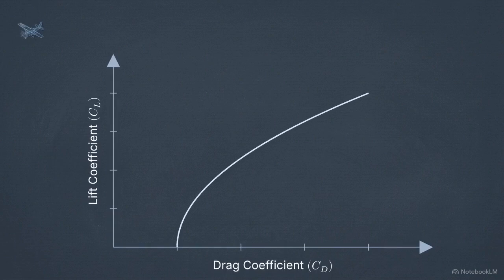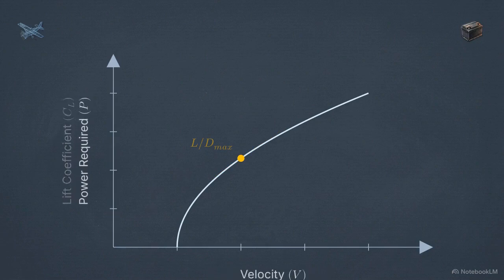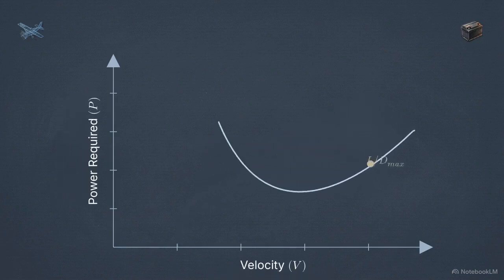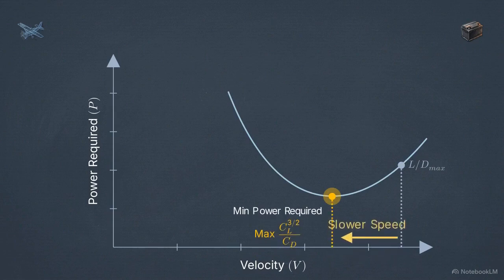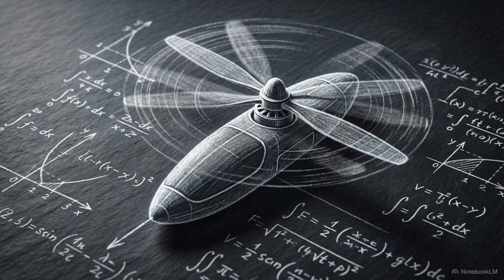If our goal was to fly as far as possible for maximum range, we would aim for this specific minimum drag point, known as L/D max. Our objective here is maximum endurance, meaning we only care about total time aloft. To maximize time, minimizing drag is the wrong approach. We must minimize power. Because velocity acts as a cubed multiplier in the power equation, the lowest required power occurs at a slower speed than the lowest drag. This specific mathematical optimum sits at the peak of the CL⁵/CD curve.